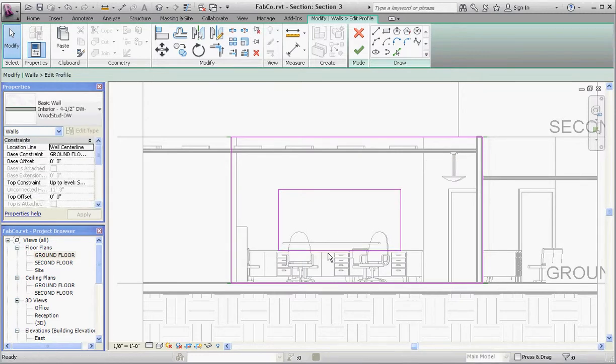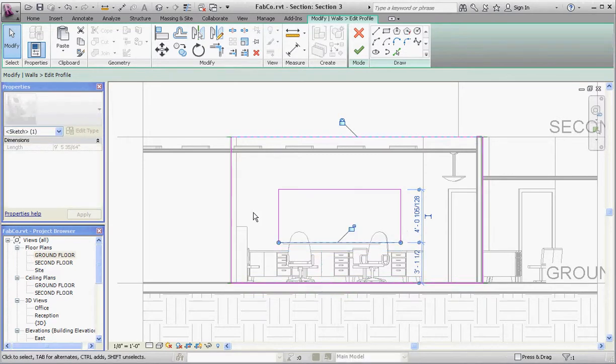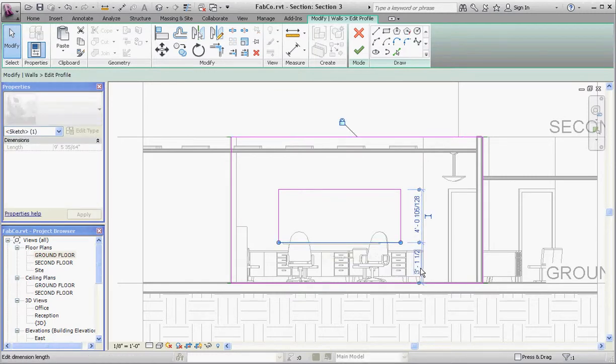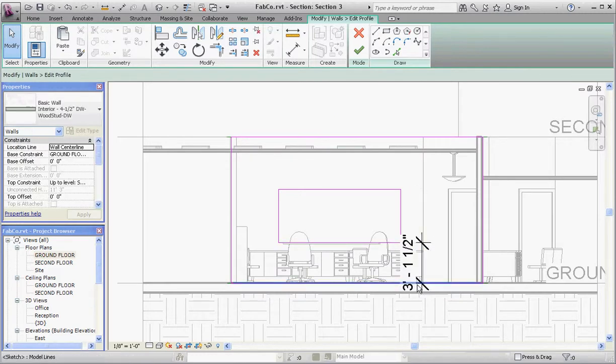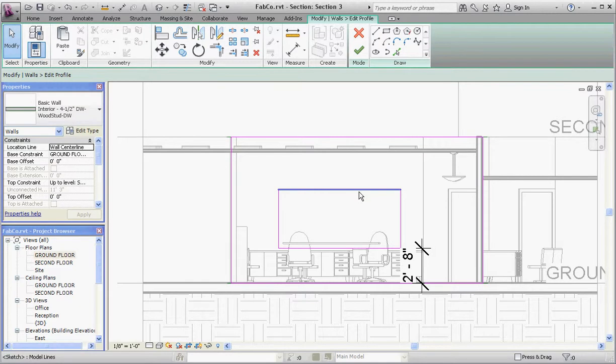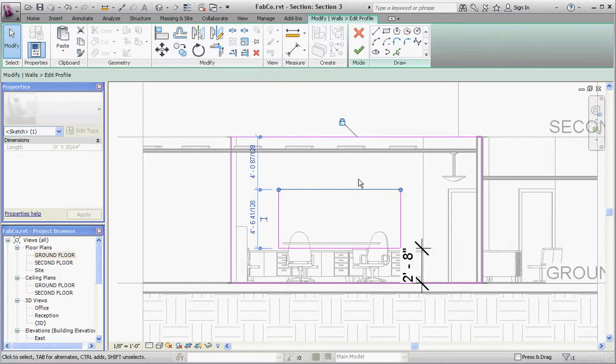So one thing we might want to do is take the bottom line here and make that a very defined distance. If you click it out, we'll get a dimension associated with that. Let's go ahead and click in that double dimension, reduce the one down. And if you click on the bottom of that line, we should be able to take that, and we'll make that maybe 32 inches. And another dimension. Let's go ahead and click on this line. Let's make this specifically maybe 5 feet.